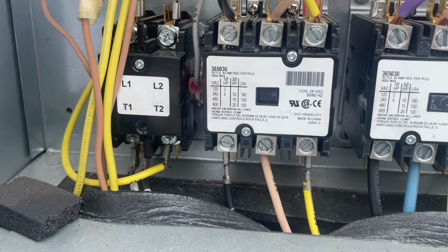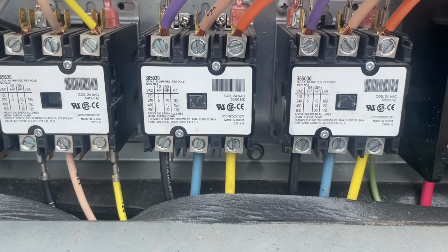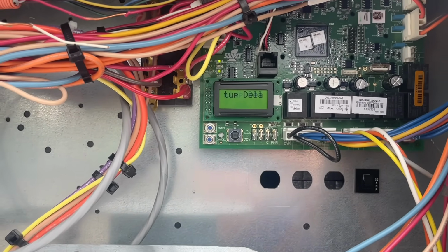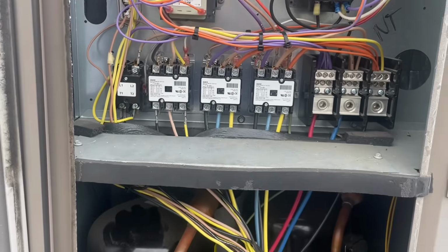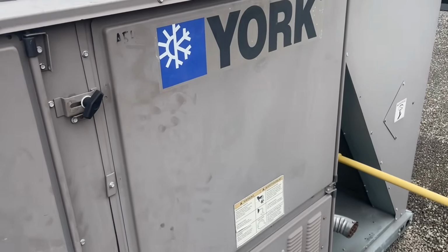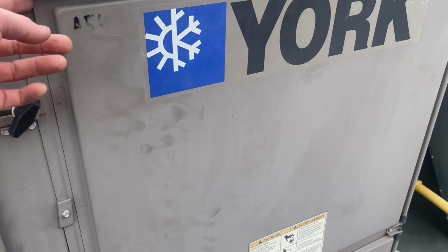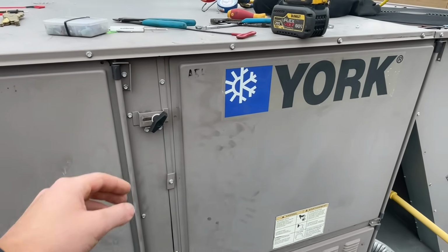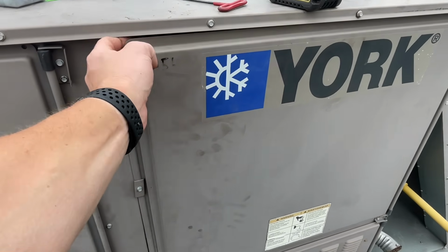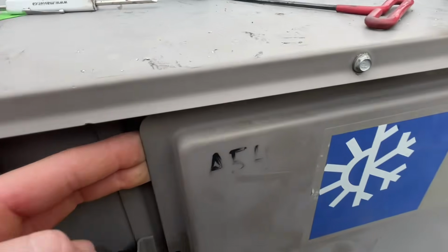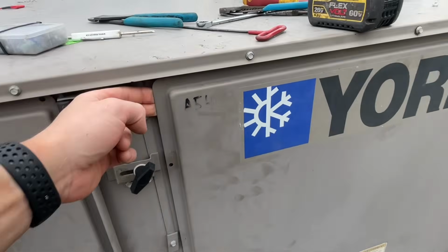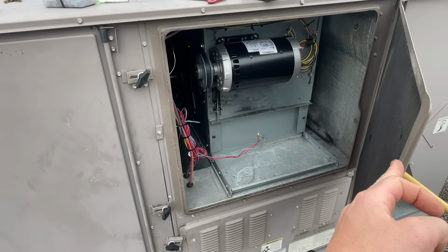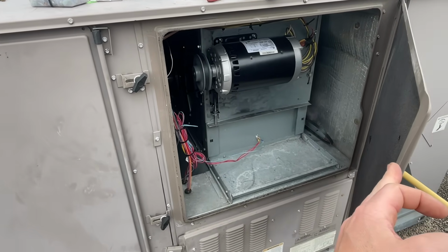Okay, so our blower contactor just energized. Compressor 1 and compressor 2 are still de-energized. There's a startup delay on the board. First things first, let's go and check rotation. So the easiest way I find is knowing this door here, which is our blower door, is on the negative side of the unit. We should have suction on this panel, which it feels like we do. You can hear the airflow. Sorry, I'm just bringing my microphone close, but. So there's a good chance this blower is going the correct way. Watch how hard this door slams.